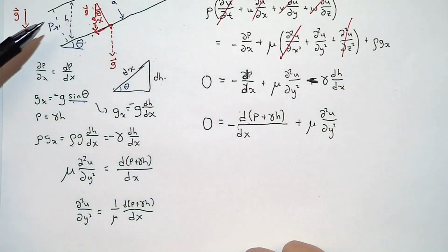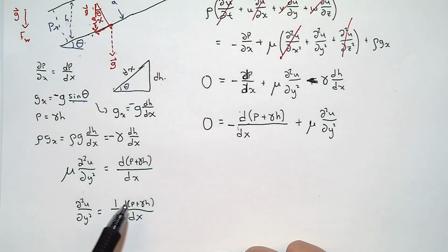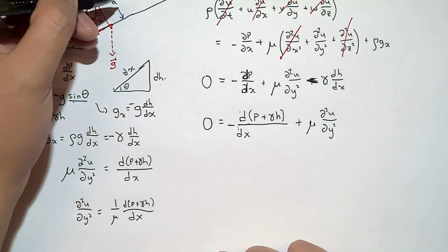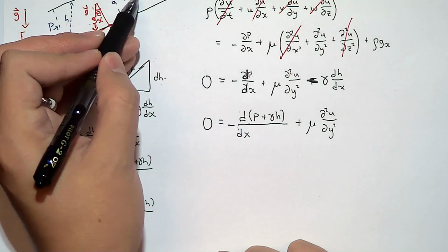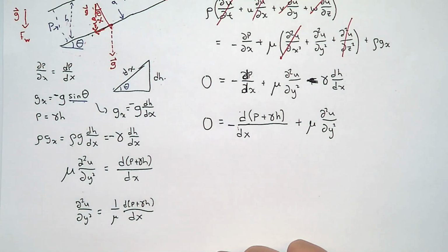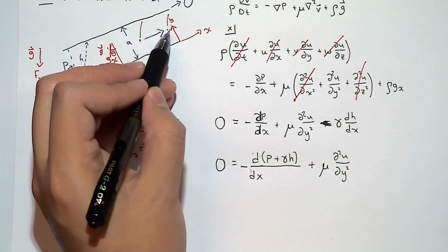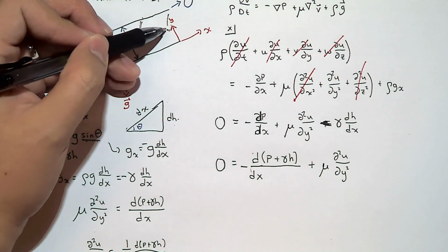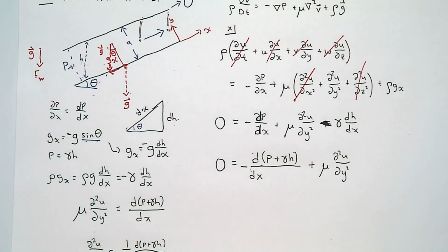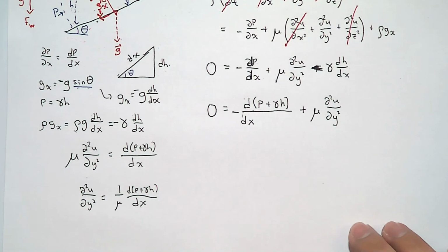If the pressure gradient is constant, the velocity is steady, right? It doesn't change with time or with the x direction. We already established that the velocity is steady. So that means that this pressure gradient is constant. Now notice, in the x direction, if I move from here along the x direction to here, does the depth dimension change? No. Okay, so that means that this is also a constant.